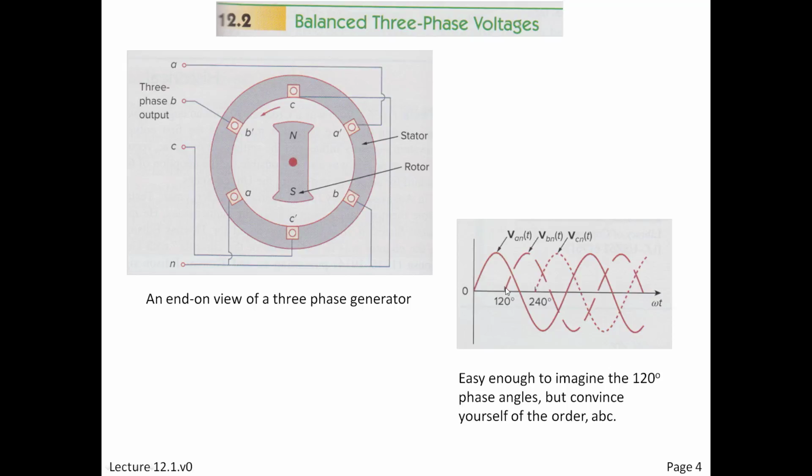So one third of the way later, if this is 360 degrees across one complete revolution and one complete cycle of the A form, one third of the way down that, or 120 degrees, begins the B shape, and two thirds of the way around begins the C shape. All right, so let's go a little further down. Let's talk about when the north pole passes A and then also passes C prime before it gets to B. Let's try that.